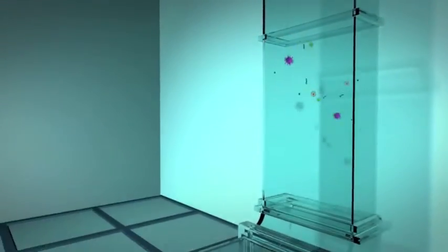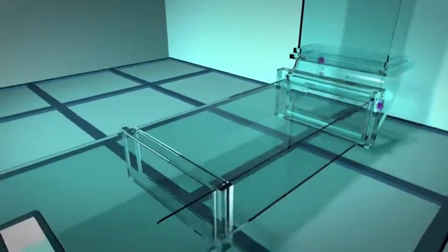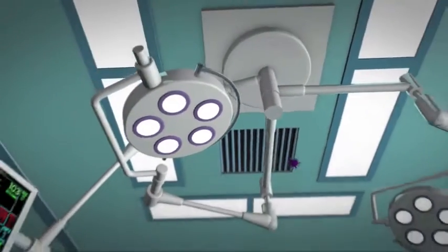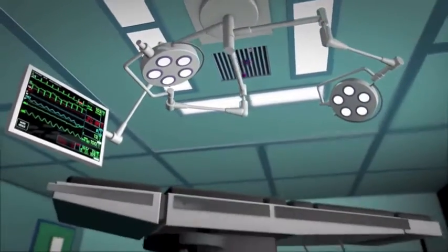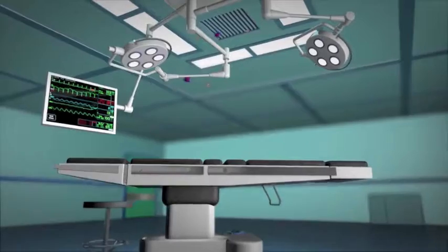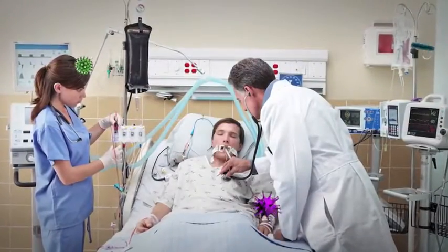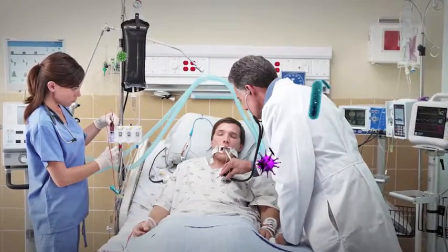With air traveling at approximately 800 feet per minute through a 24-inch square duct, we have 80 million particles. So, on average, 0.003%, or 24,000 of the particles per minute, might break through the HEPA filter. If only some microorganisms break through, they can infect the patients.